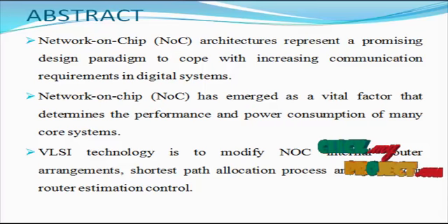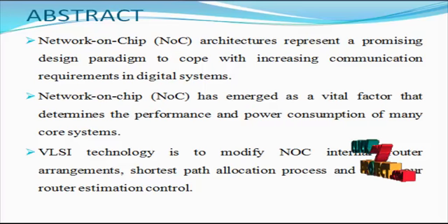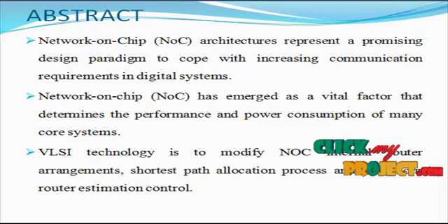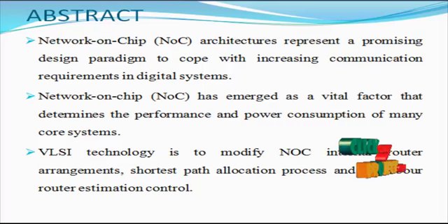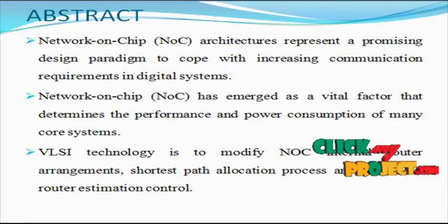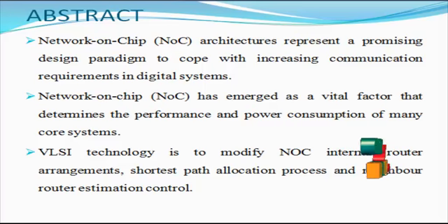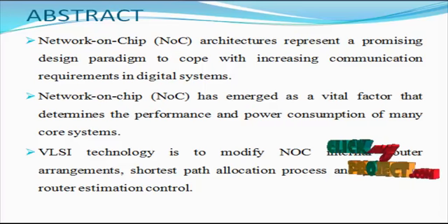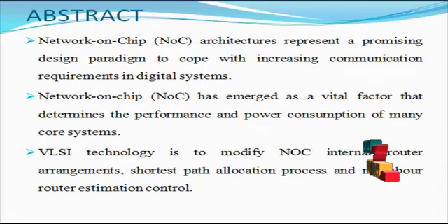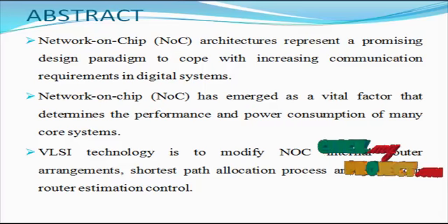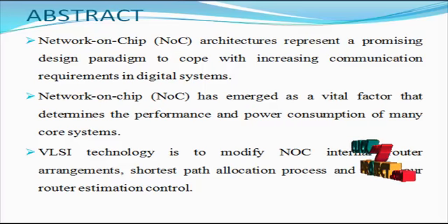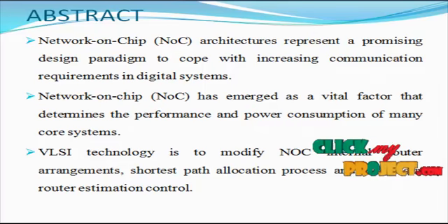Due to 3D NoC manufacturing technology limits and design complexity constraints, current 3D NoC research focuses on simple 3D mesh topology. Ideal analysis shows that the 3D mesh XYZ deadlock-free algorithm achieves better system performance under a middle size of interconnect and typical traffic pattern, but in a larger system with increasing cores and various specific applications, the traditional 3D mesh framework leads to extra delay and reduced performance.